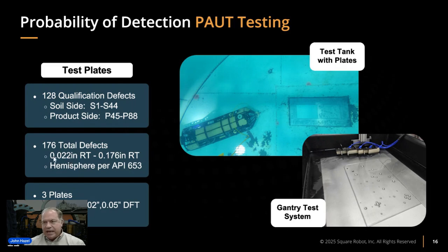And most of the time, what we're finding in contact testing is normally around 0.040 was the limit of what the thickness that you'd be able to resolve. But in our scenario with the higher frequency transducer and the added standoff that we're applying here, we're able to measure down to that 0.022 and possibly a little bit thinner. We didn't quite get to the limits of the minimum resolvable thickness here. And we actually had three different plates.